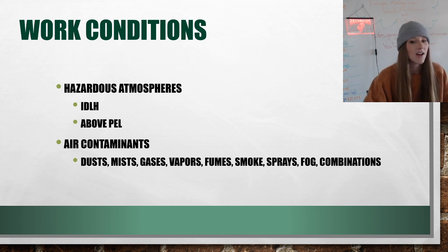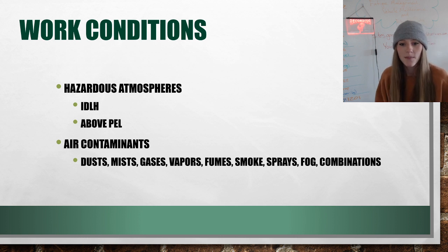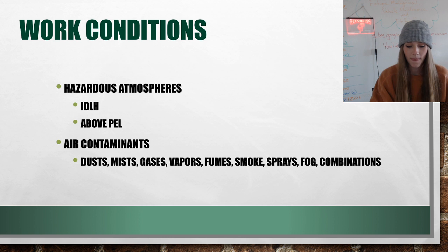IDLH is anything over limits, or under 19.5% oxygen as well is considered IDLH. If you don't know the condition of the atmosphere you're in, if it's unknown, then it is automatically IDLH. It could be completely fine to be in it without anything, but if you don't know, it's got to be considered IDLH. Some different air contaminants that you can encounter include different kinds of dust, mists, gases, vapors, fumes, smoke, sprays, fog, and combinations of those things.